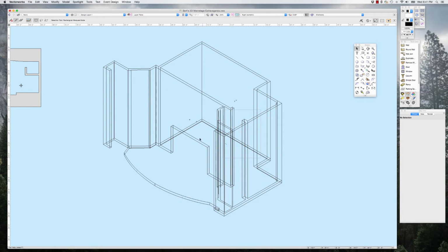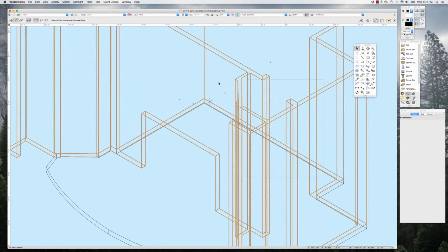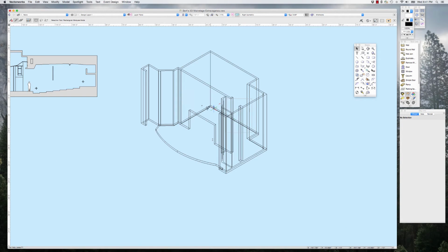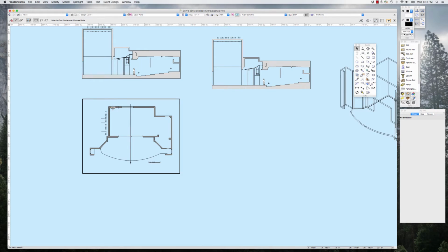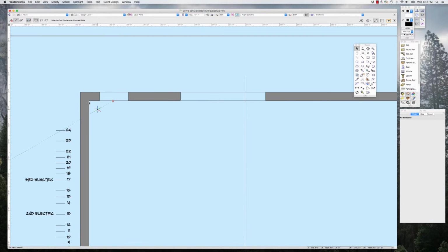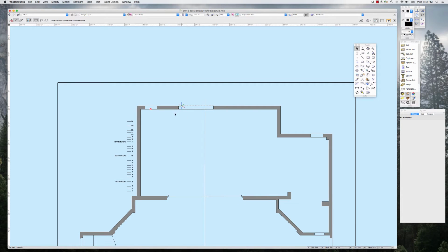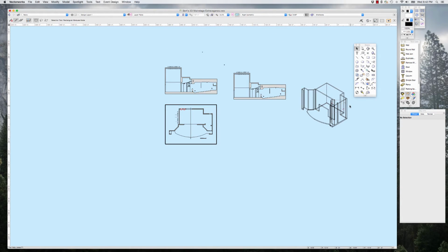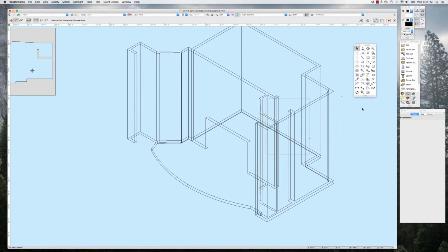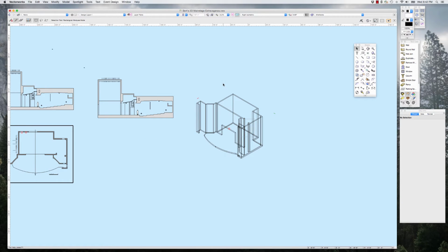If you wanted to do that, you would do it the same way. You would draw, using the 2D plan, rectangles using a locator so that you know where to put them on the other side, extrude them the right height, subtract them from the walls, and then if you wanted to add the actual doors in, you could do that. But I don't see the need. We really don't need to do that.